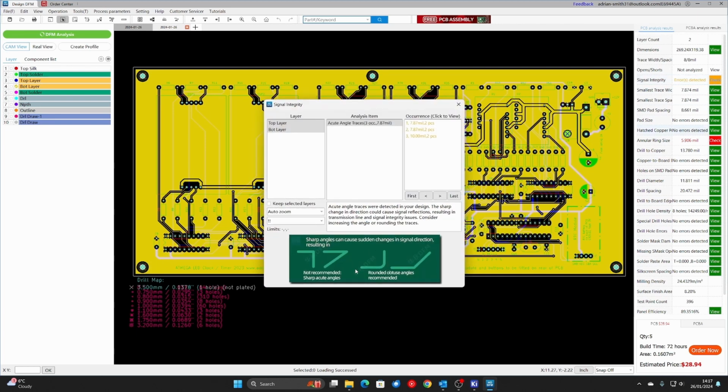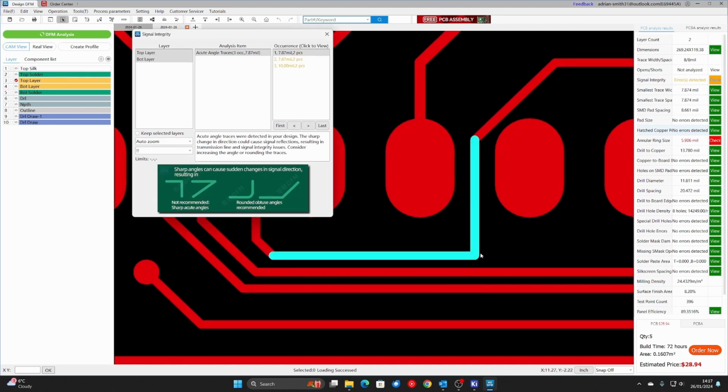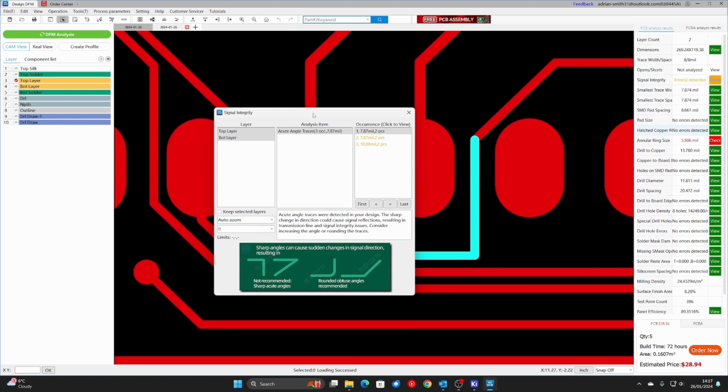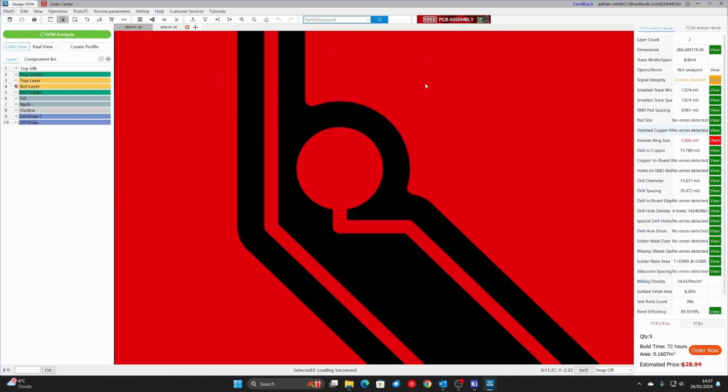There, look. I've got some PCB traces there, right? That's a big no-no for good signal integrity. It's about PCB design practice. For low frequency signals it's fine, but for high frequency, you really need to design it properly. So obviously KiCad isn't going to pick up on that, but this software will. It's good design practice to not do that.